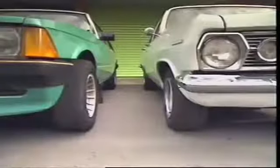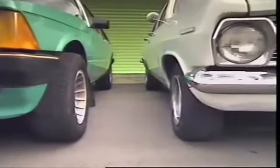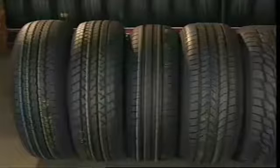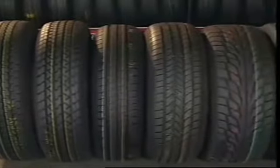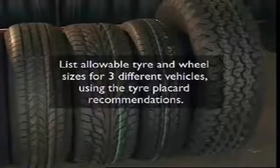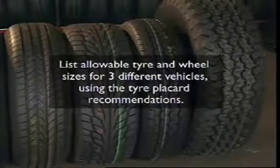Regulations cover the allowable dimensions for wheels and tyres on a particular vehicle. These dimensions are usually set out on the tyre placard attached to the vehicle. Incorrectly selected wheels and tyres can overload wheel bearings and change steering characteristics. The tyre placard lists the wheel and tyre sizes approved by the manufacturer for the vehicle. Using other wheels and tyres may be illegal. List allowable tyre and wheel sizes for 3 different vehicles using the tyre placard recommendations.